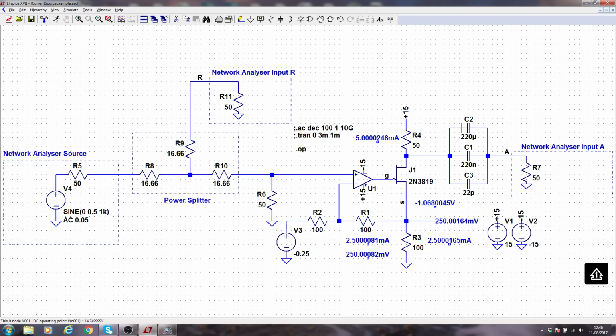It will be, if you were in the 118 lecture 1, a spiral of two bits of foil, probably made from aluminium or something like that, with something akin to peanut butter in between. It's not really peanut butter, but it's got a reasonably high permittivity, and we make the capacitor by the usual method. It's epsilon naught epsilon R A upon D, where A is the cross-sectional area of the plate and D is the distance between the two. And epsilon R is the relative permittivity of the dielectric medium, which is, in quotes, the peanut butter.